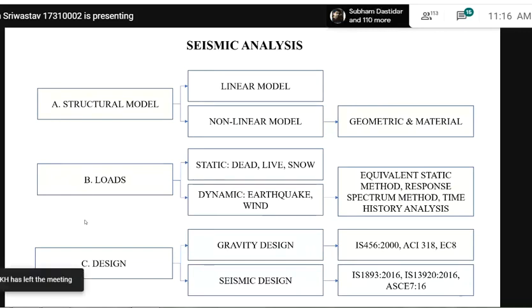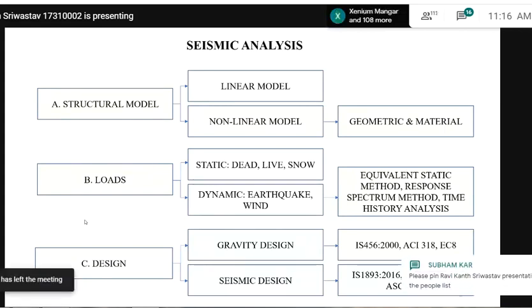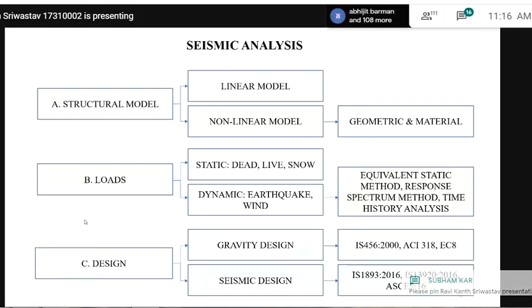So we take the help of software like SAP 2000 or ETABS, and the model which we use in practice, like whatever consultancies are doing, they are doing all the linear model. Basically there are linear models as well as non-linear models. More realistic is the non-linear model. I will go into this in more detail in next slides. Non-linearity, as it is shown, can be because of geometrical non-linearity as well as material non-linearity.